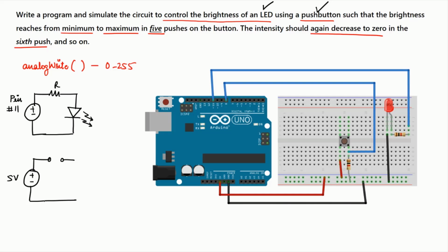So we've got 5 volt here. This is connected to the ground. There's another resistor connected to the ground. And this is where the push button is. So when I press this, when this button is pressed, these 2 terminals actually get connected to each other. Right now they are in open circuit, and we'll see this just in a while, how they are open circuit, how to check this. So these 2 are connected internally already, but this terminal and this terminal will be connected only when this button is pushed, right?